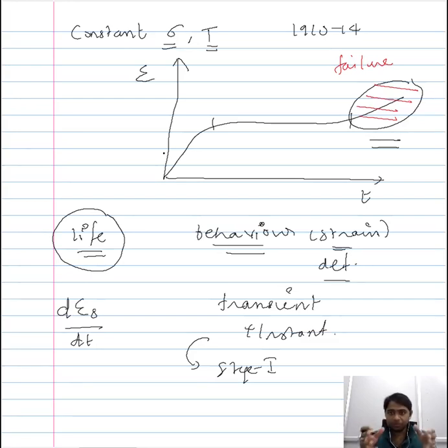Meaning, when you begin to employ a material in an application, the load is instantaneously imposed on the material and the material begins to deform. So this is observed in stage 1 of the creep. The deformation introduced by stage 1 cannot be ignored, because once you introduce the material, it experiences a mechanical condition at a given temperature, and only after stage 1 do you get into the steady state case. So this stage cannot be avoided in an application.